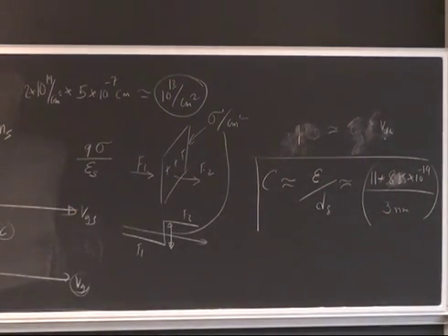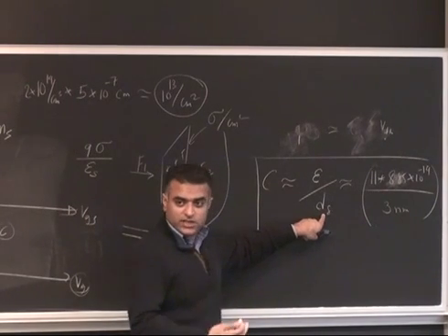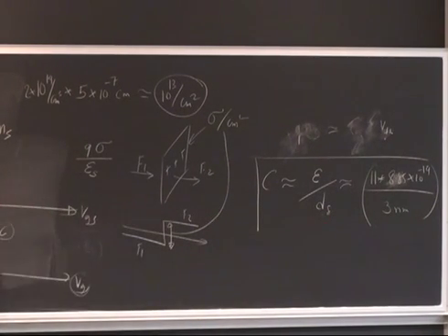So when you do a measurement, it immediately tells you what you have grown. You don't know exactly. You have planned to have 5 nanometers here or 10 nanometers here, but you don't know exactly what has happened. You make this measurement, and you right away know what this d delta is. Kind of an interesting way to measure it after you're all done. Does that make sense? Thus the capacitance, when it flattens out, is called the zero bias capacitance. And the carrier density, as I was mentioning, is here.